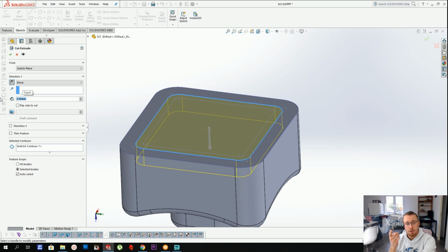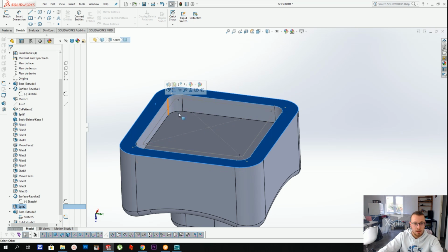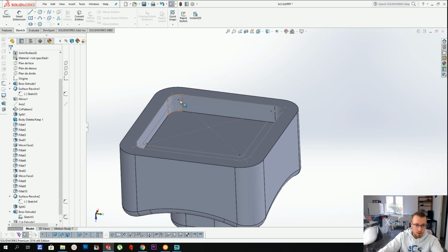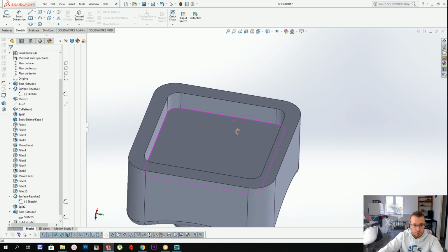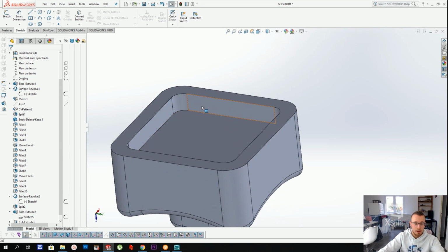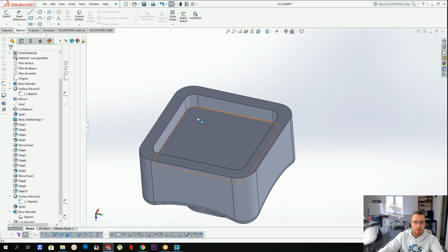That's a tolerance there, so that the cap is resting on that face and not on the inner face. I want the cap to rest on that face and not that. So here I've extruded it by 2.5 millimeters. And this is the female cap, and the male cap is on top.